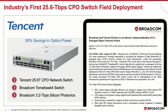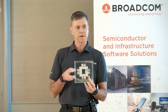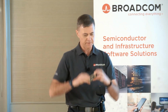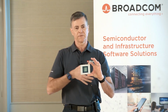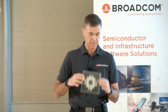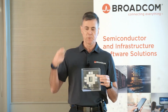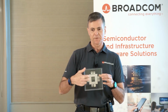One thing you can look at afterwards, it's a little bit heavier, is a Tomahawk 5, what we call Tomahawk 5 Bailey. In this particular implementation, we decided to make it all optical I/O. Whereas this right here is a Tomahawk 5, which I think is what we showed at the last Network Field Day, announced last August and shipping in production now, there are no optics on this. Everything is out the balls on the back. In the case of TH5 Bailey, it's the same switch silicon. We just bolt on the optical engines around the side. So all those pluggable optics, actually 64 800 gig optical modules, are integrated into this package.